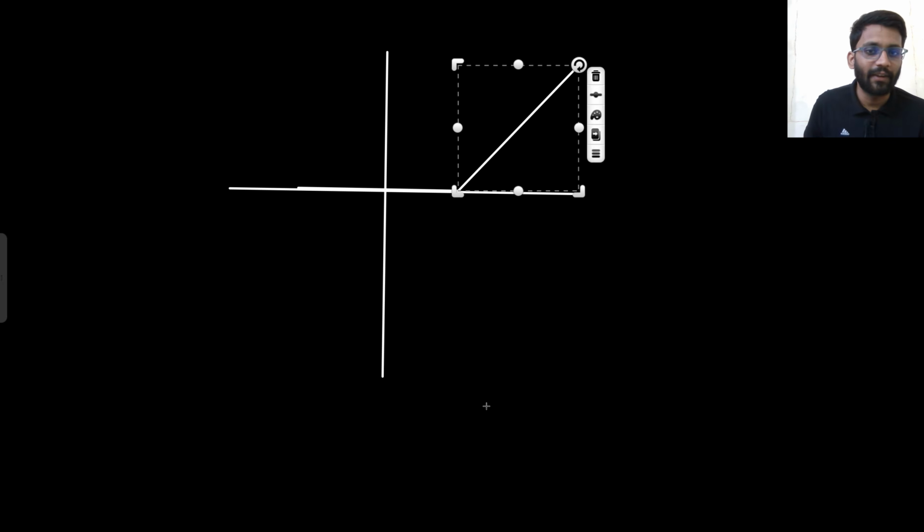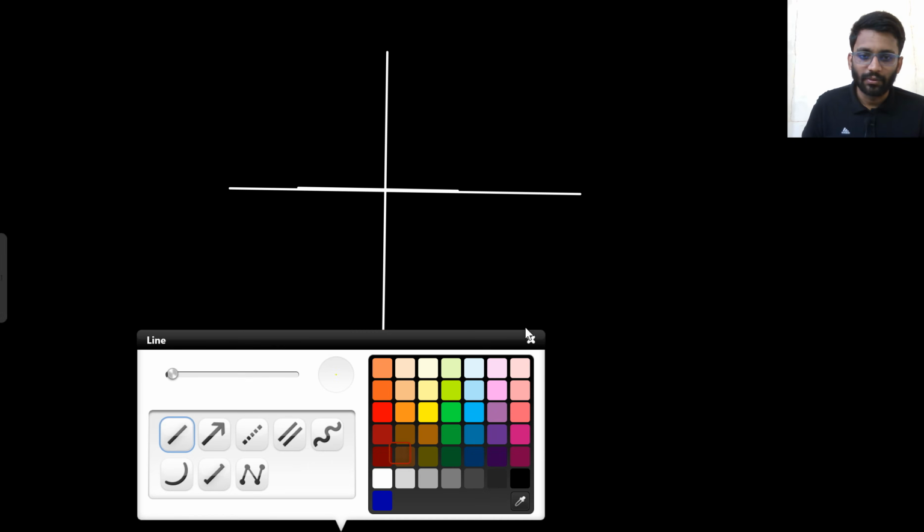You could say the diode is off if you were studying this characteristic. Yeah. So if you were studying this characteristic, then you would have said the diode is off. So here it would give me 0 voltage drop. It would give me basically nothing. So if you were studying this model, then you could have said that, sir, here the diode is off. You can replace that diode with an open circuit. But the model is ideal.